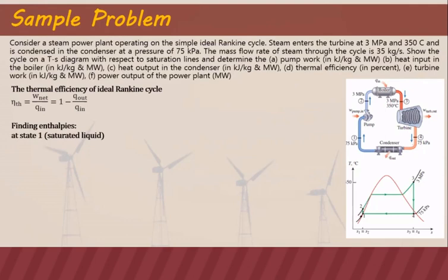At state 1, just like what I said a while ago, this is a saturated liquid. This curve here is the saturated liquid curve. That's why this is a saturated liquid at state 1. To find the enthalpy when it is saturated liquid, all you have to do is look at the steam table.